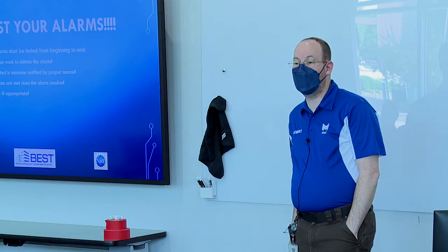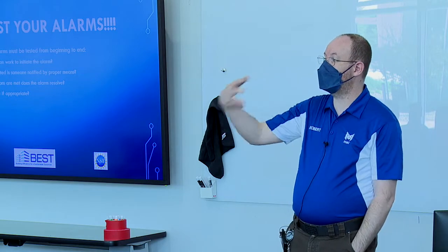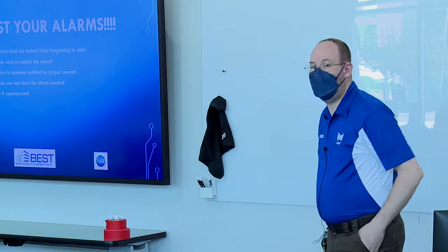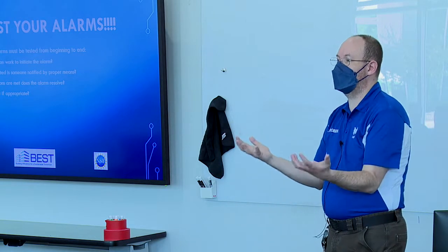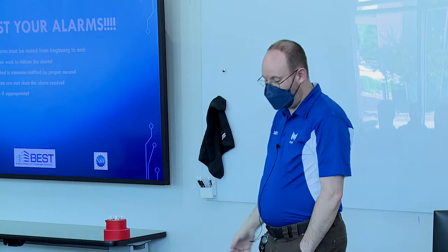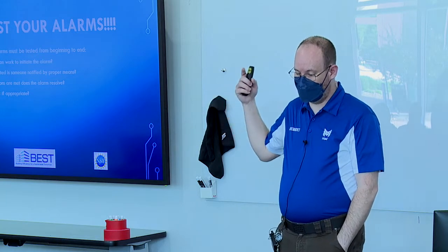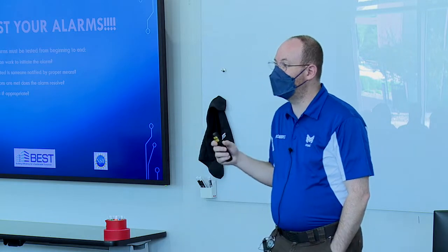come on, don't be that lazy. Give it a useful message. Air handler 1, supply fan failure. Okay? Or you can't use room temperature out of range. Okay? That's great. What room temperature? I have 800 rooms in this building. Which room is out of range? Those types of things. Okay? Those need to happen. They need to be useful messages.